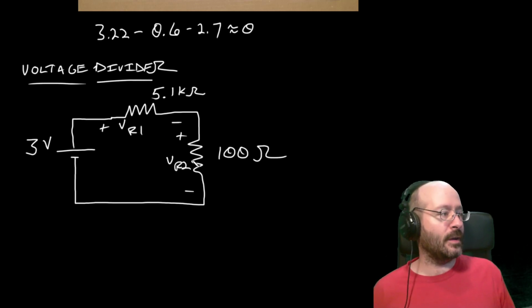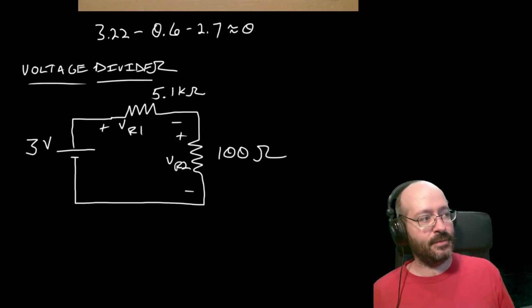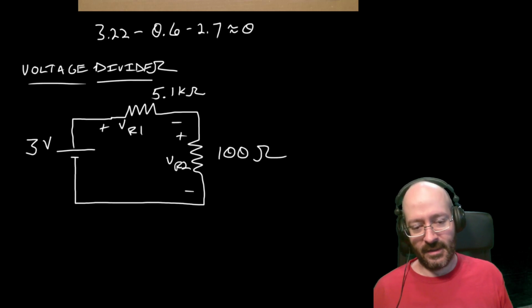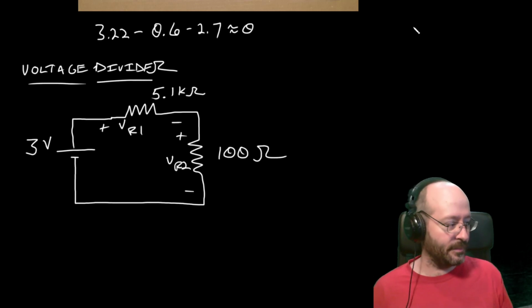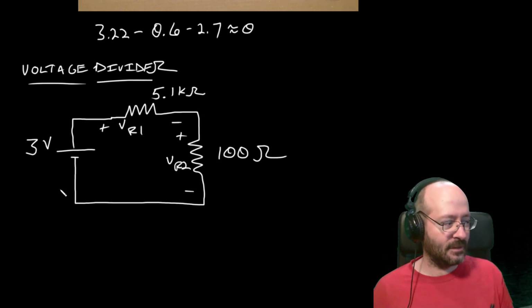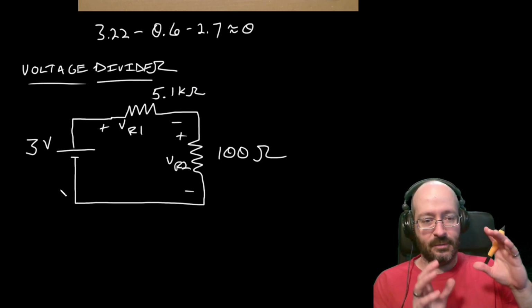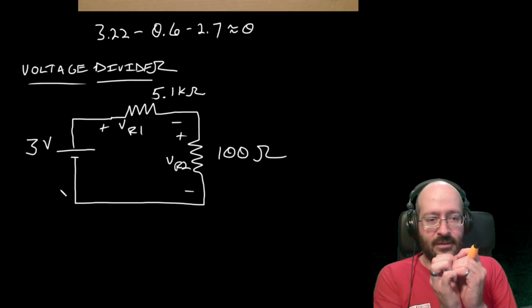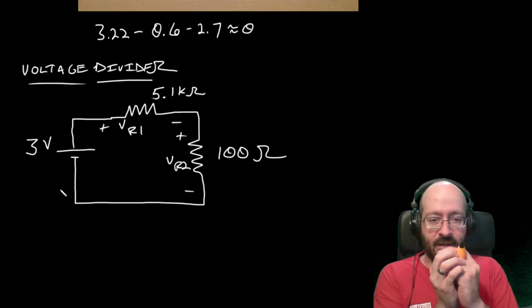This circuit shows up everywhere thanks to another theorem called Thevenin's theorem, another French guy, dead French guy, where he said we can reduce any linear circuit into a voltage supply and a series resistor. So a lot of times we use Thevenin's theorem to reduce circuits to a manageable point. We say, okay, all of this stuff isn't changing.